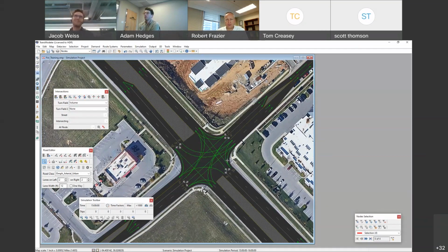It is tied to the links. But at the same time, if those links get broken in any sense, your turning movement table does not correlate. So if we were to change that to a roundabout, those volumes would not effectively get brought through the network correctly. That's the beauty of using an OD table and setting your externals or even internal nodes, so that you never really have to touch those in your simulation, and all that OD that's generated through the calibration and validation at the beginning of your project with your existing model is used.